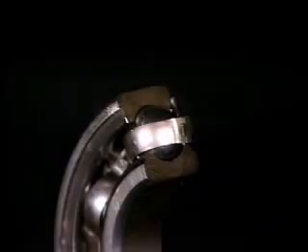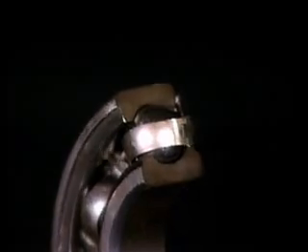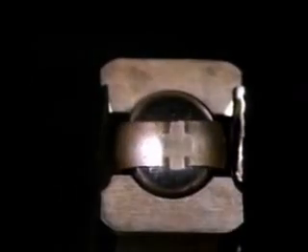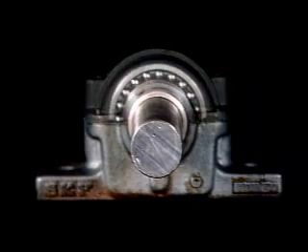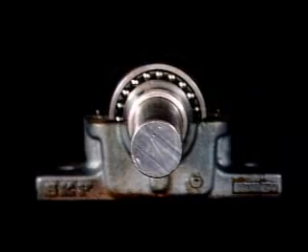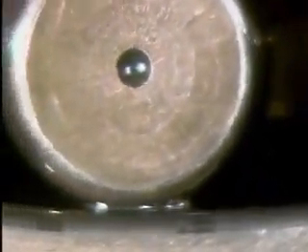These ball bearing rings have been cut in half to show their internal construction. The balls travel in grooves in the inner and outer rings. The grooves are called races. The outer ring of a rolling element bearing is fixed in a housing, and the inner ring fits tightly around a shaft. As a ball or roller rotates between the races, it draws a film of lubricant between it and the races. This film of lubricant separates the rolling element from the races.